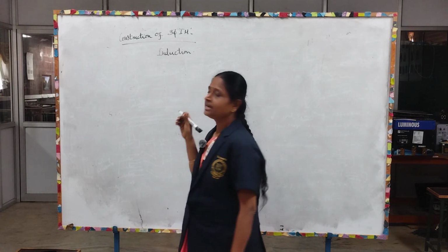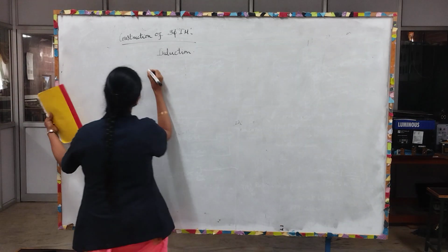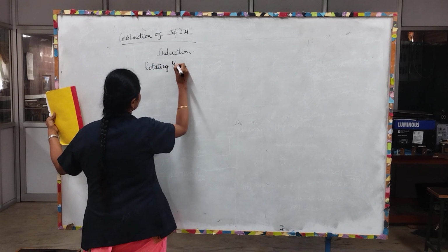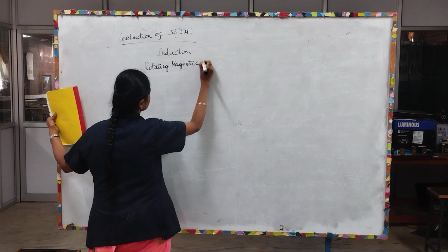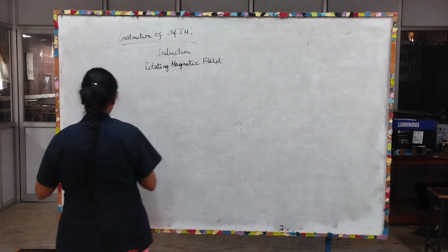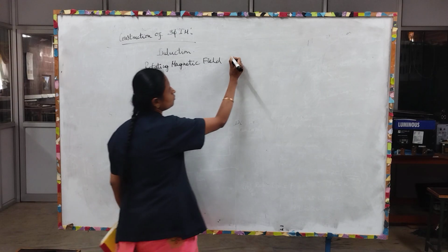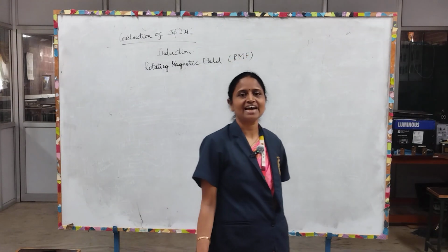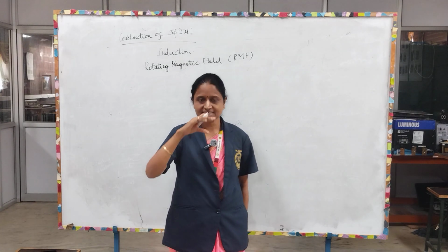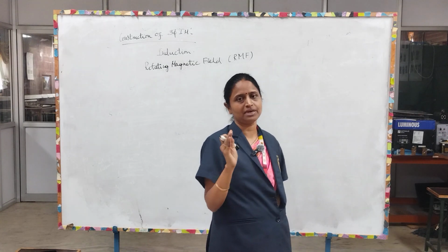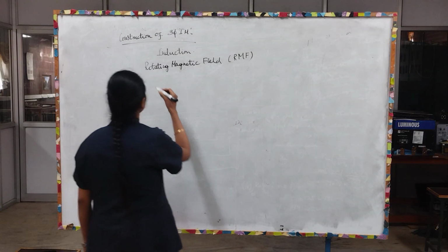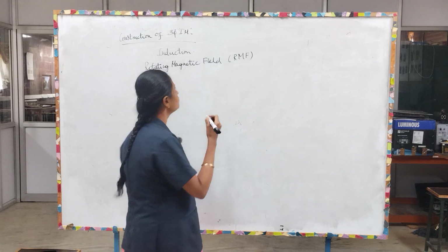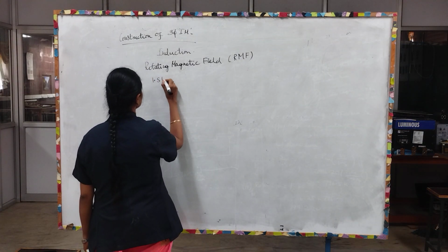So the induction motor works on the principle of the rotating magnetic field. What do you mean by a rotating magnetic field? It is also known as RMF. RMF is nothing but the field or flux having constant amplitude, with its axis continuously rotating in space. That is called RMF. In the construction of a three-phase induction motor, we have to discuss the stator as well as the rotor.